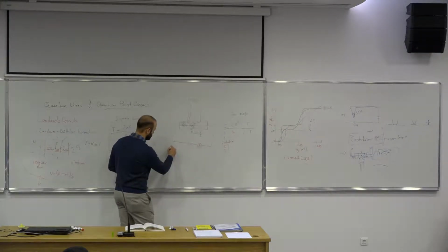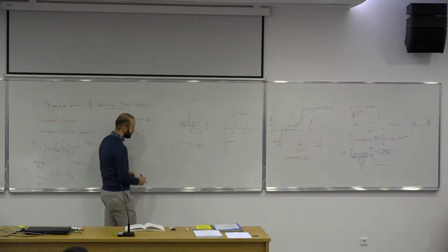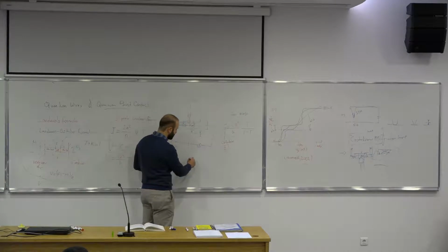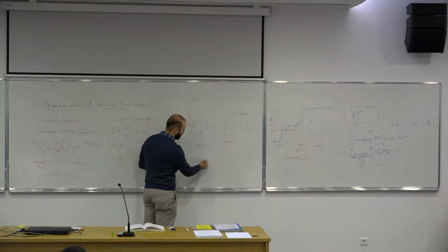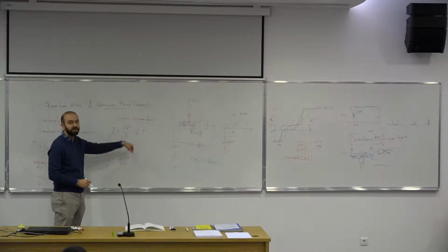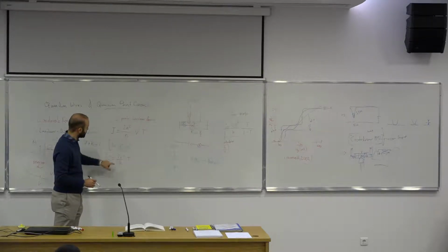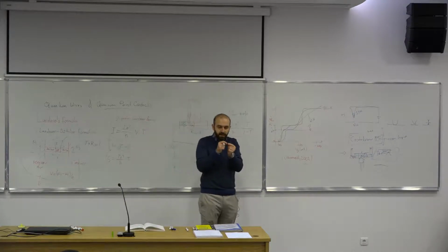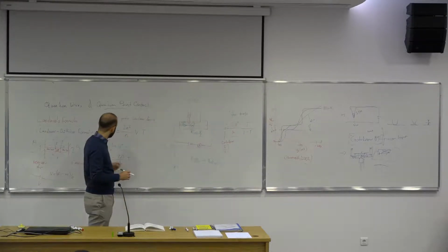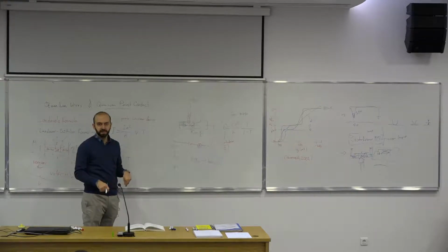So we have this something called quantum point contact. Last lecture, that's what we did. And the width of this quantum point contact is critical from transition to classical regime to quantum regime. So rather than diffusive, as you make it narrower, you go to ballistic transport. And in the case of ballistic transport, this is the formula we got. The conductance, this term, is given by such an expression. It's quantized. And what you do in that experiment is that by pulling it apart, you create a narrower and narrower channel gradually. And as it becomes narrower and narrower, at some point you start electrons doing this ballistic transport, and the conductance is quantized. Okay? That's the information, guys.